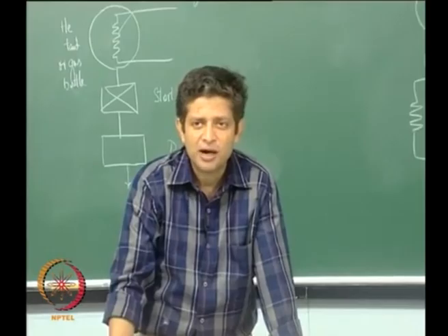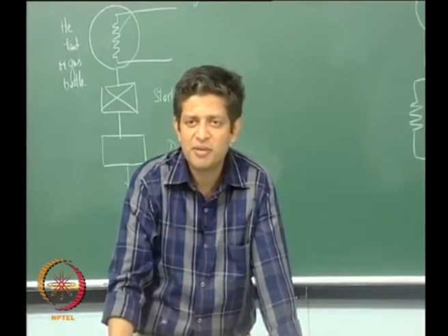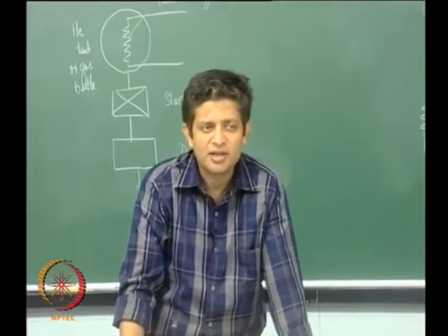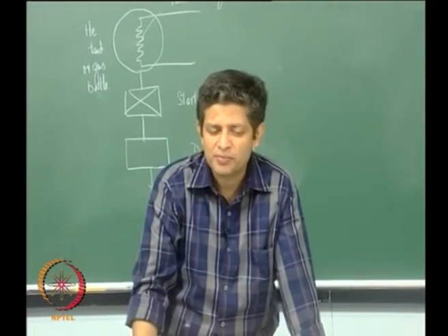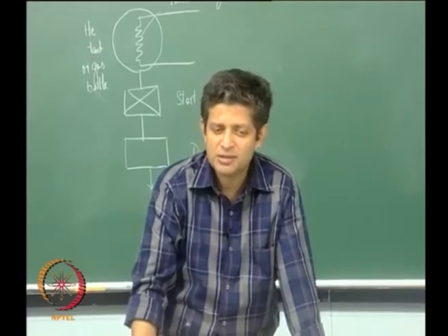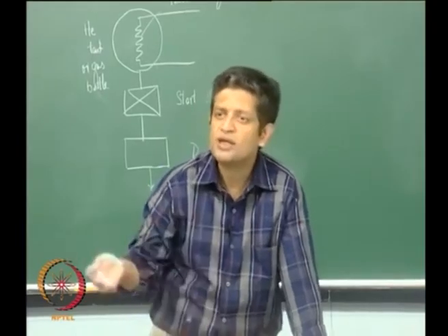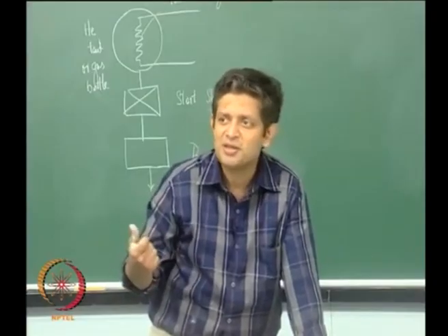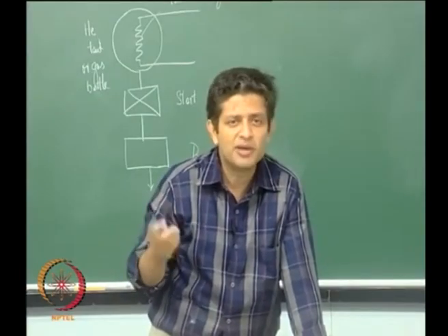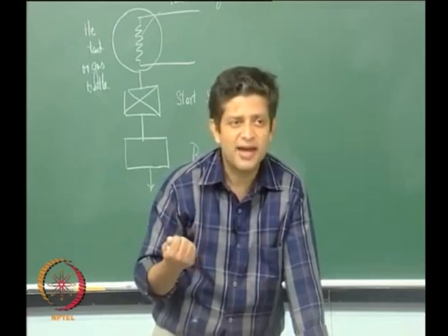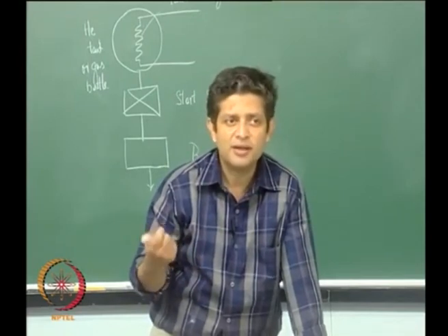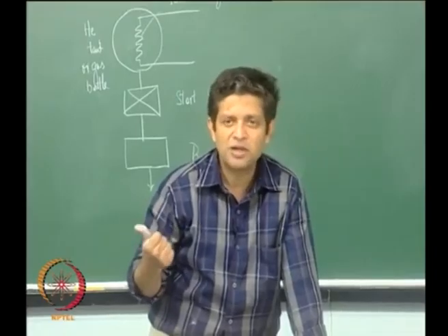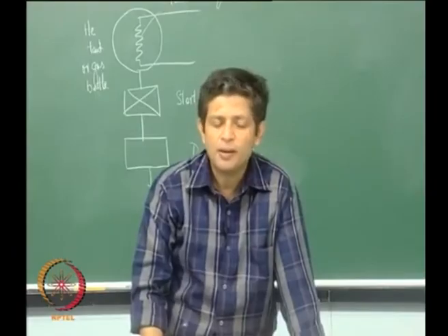So if you are increasing the pressure to 350 bar, it is like 350 times the density of air, which is around 350 kg per meter cube, right. This density is very low, so you need a large volume, and therefore the weight of the pressurant tank goes up, because if you have a large volume, remember the design of the tank, it is PD by 2T. So the thickness of the wall goes up, and therefore your weight will go up.